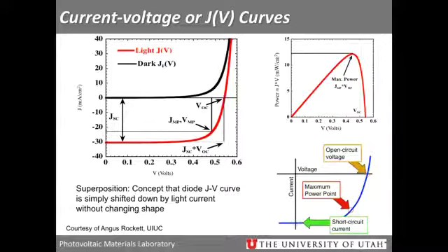So what this is showing here, if you remember the plots that I showed of the maximum current, the maximum current in a solar cell will always be at 0 voltage. It's a short circuit current. The maximum extractable voltage will always be at an open circuit voltage when there's no current flowing. So your maximum power point is a function of what your JV curve looks like.